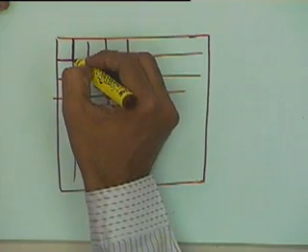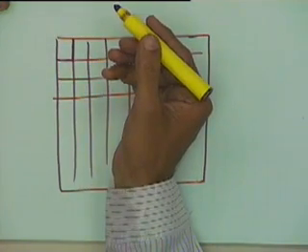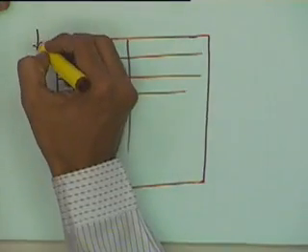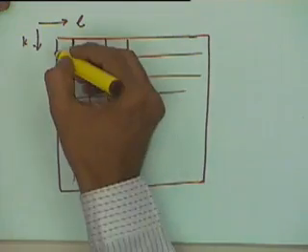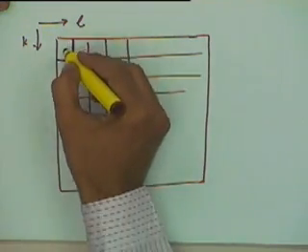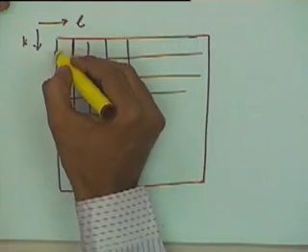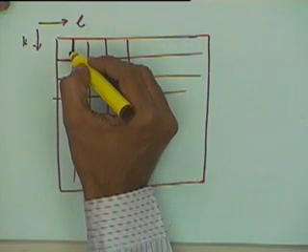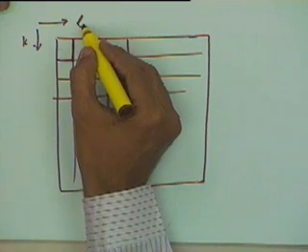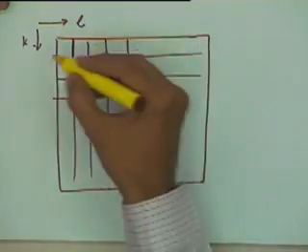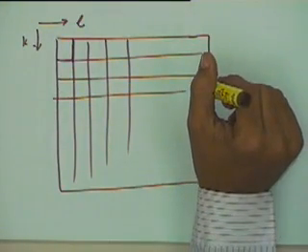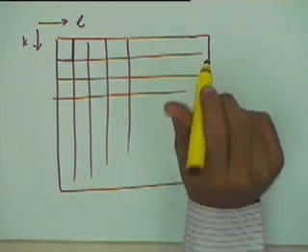Each patch will have a degree depending on the degree of the B-spline surface. So if you are taking a degree k here and a degree L in this direction, then each of these patches will have a degree k and degree L, and the number of points controlling each patch will be governed by these parameters k and L, while the total number of points might remain anything. So this is how we can define B-spline surfaces. Any questions on B-spline surfaces?